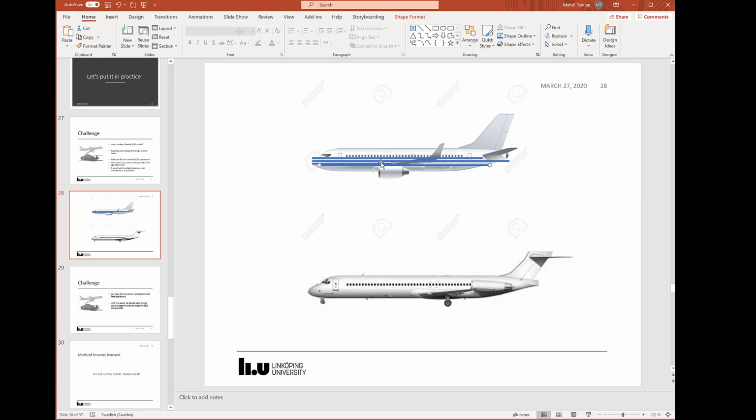And then the vertical tail is, as you can see, at the end of the fuselage, but probably it has some kind of offset. So I'm going to put some offset from the leading edge of the vertical tail, where it should start. So from the end of the fuselage to the leading edge of the vertical tail.